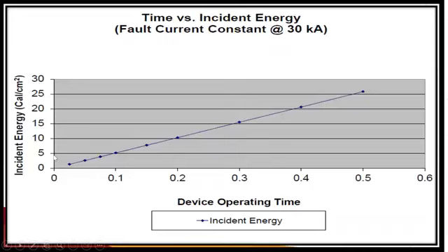So at that particular location, 3 or 4 years back, I performed the complete risk assessment of my system, and I determined that the incident energy at this device clearance time is 5 cals per centimeter square. So I performed the risk assessment and put the labels there. Since then, all the people who have to perform the switching operation or some justified work on those pieces of electrical equipment know that if I'm wearing an 8 cals per centimeter square or a 12 cals per centimeter square suit, that is safe for me because the incident energy at that particular location is 5 cals per centimeter square.